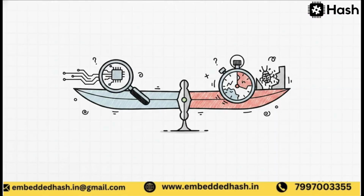Aside from the physical hardware probes, we also lean heavily on software tools, with UART logging being a classic. It's basically blasting print statements out of a serial port. Now, UART logging is super easy to set up, but it is a massive double-edged sword. If you push too much text out of that serial port, you can actually choke the CPU and alter the system's real-time timing. It's the classic observer effect. You might end up fixing or hiding a timing bug simply by slowing the system down to observe it.